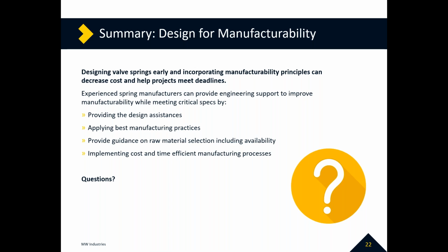So that goes to using spring industry tolerances, again, versus machine tolerances. We're going to tell you right up front what those are and what tolerance that spring is going to see on the OD, ID, free length, and load.